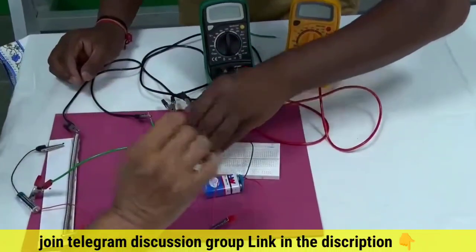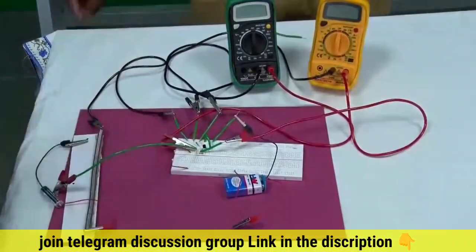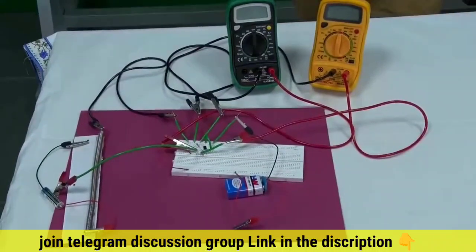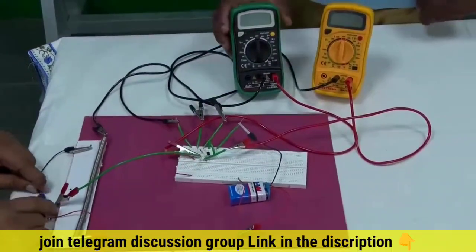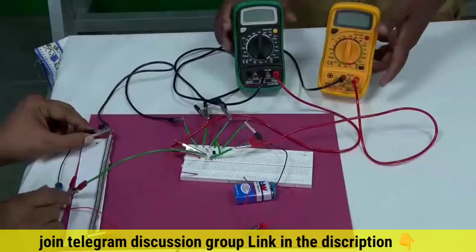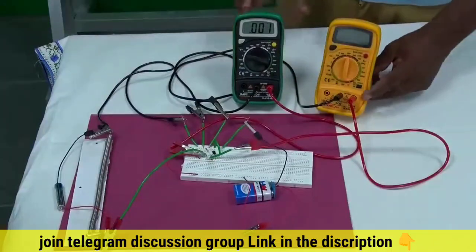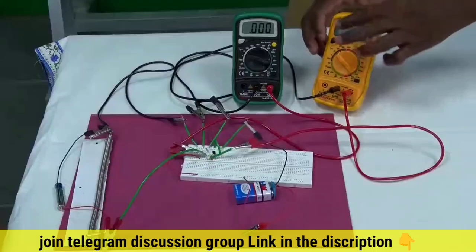And you can connect this thing here, right. So, now it is connected to the collector. Okay. So, the circuit is complete. So, let us start working on this. This 1.5 volt battery I am now connecting, all right, and put this in DC voltage 2 volts range, and the other one, the output, in 20 volts range.